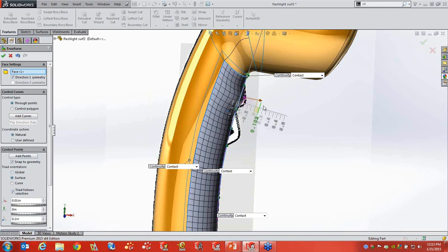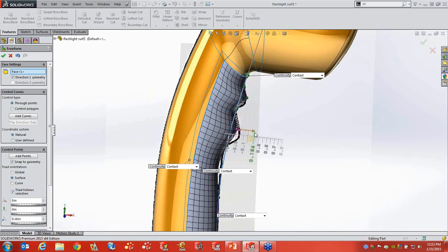Now another thing that I like, and if you've used any spline tools in SolidWorks, they've made some changes over the years as far as how to control the curvature of the spline. And you can see if I'm pulling these points, other things are moving. It's a little bit harder to match what you're trying to do. However, in splines we have the ability to use the control polygon, and that control option is also in Freeform.